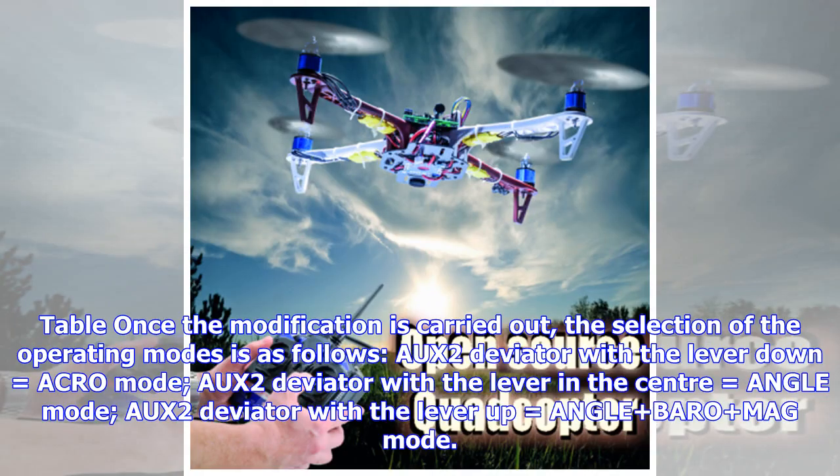Table. Once the modification is carried out, the selection of the operating modes is as follows: AUX2 deviator with the lever down equals acro mode, AUX2 deviator with the lever in the center equals angle mode, AUX2 deviator with the lever up equals angle, baro, mag mode. The definition of these functions is carried out by using MultiWii and by clicking on the small squares corresponding to the function you want to activate.